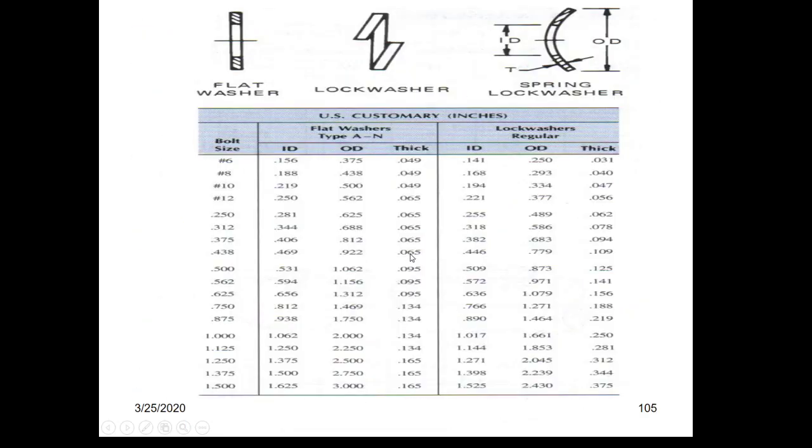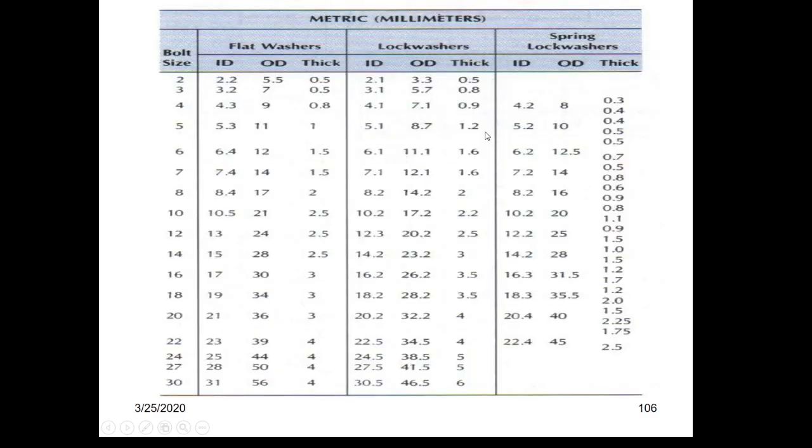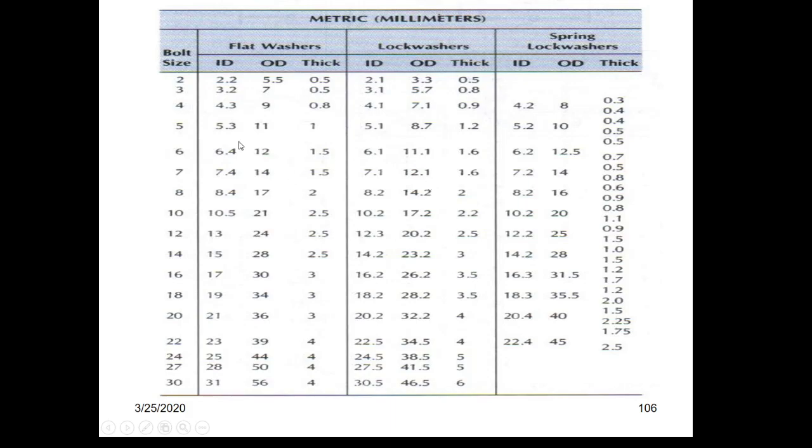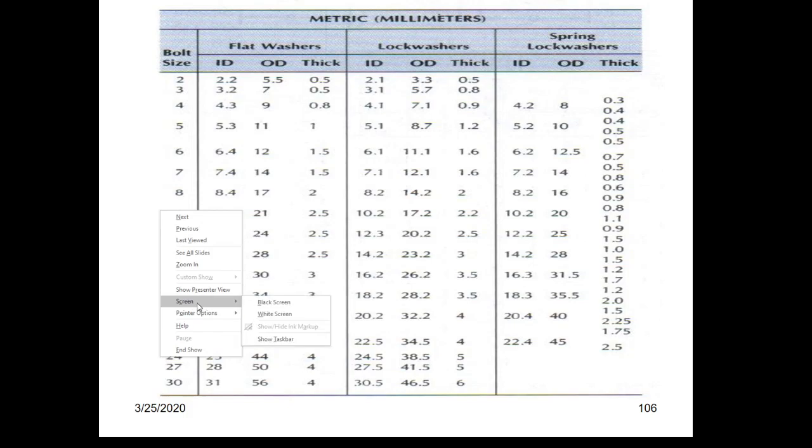And then a table. It says bolt size 10. Nominal value for the washers is bolt size. Okay. And then this is British, American series. This is metric series, bolt size 10. Okay, follow this row,